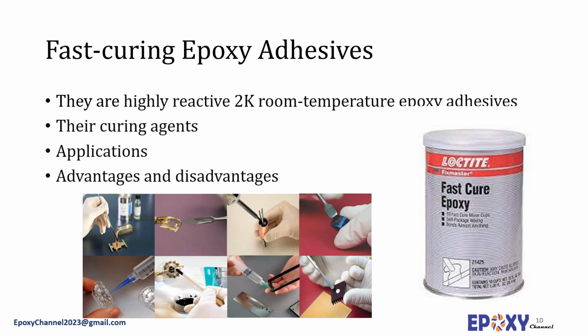Fast curing epoxy adhesives, however, suffer from a relatively higher shrinkage and brittleness, which yields lower peel and impact strengths compared to ordinary slower curing epoxy adhesives. Their curing yields higher exothermic temperatures, which may impose overheating risk and affects the final properties of the epoxy adhesive. In addition, due to their higher reactivities and short working time, they are more difficult to handle and apply, which results in higher wastage and variation in cross-linking density. Finally, due to their higher reactivities, these systems can impose higher health risks to the workers, for example, skin irritation problems.